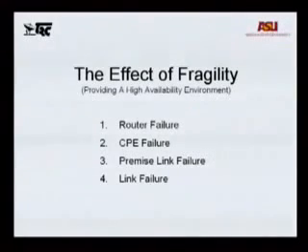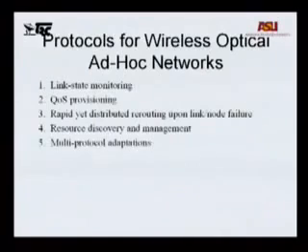You can have different kinds of failure: router failure, link failure, and so on. For the protocol for the wireless optical ad hoc network, we look at link state monitoring, we provision quality of service, we have rapid yet distributed rerouting upon link and node failure, resource discovery and management, and multiple protocol adaptations.